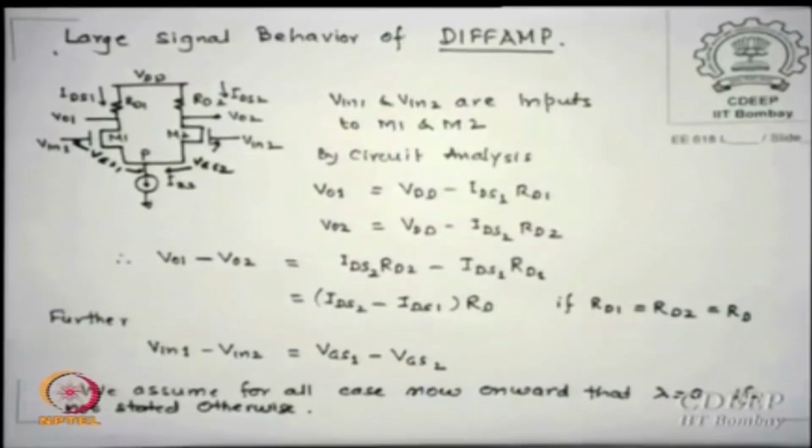For simplicity, lambda is taken as 0 for all analysis till stated otherwise. Okay. Is that okay? Please remember, lambda can be taken care of. All that will happen is, nonlinear terms will start occurring under roots and squares, and then analytical solutions will not be very easy to understand. We are not really designing with them, we are using it to explain something, and since lambda is anyway 0.01 or 0.04 or 0.05 kind of values, it will not drastically change the physics.